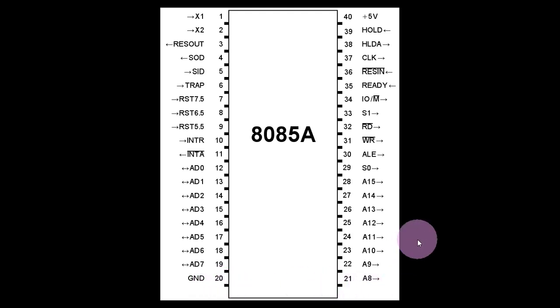After that, is there any other requirement for this IC? You have given it voltage and proper ground, so what else does it need to operate? If you see the ICs of the AND gate or OR gate that you might have seen in your digital logic course, which contain 4 to 5 gates per circuit, those ICs start to operate when you provide them power. But with a microprocessor, the condition is different, because the microprocessor operates on a certain clock.